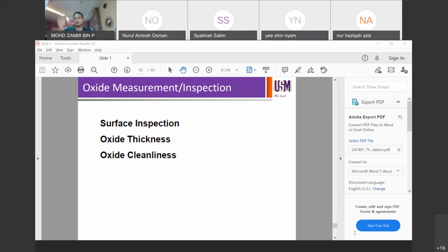So that particular lot is gonna be on hold due to the particle count failing the spec, right? Failing the process spec. So maksudnya selagi mana you tak troubleshoot the problem, whether it's due to the process or the recipe or the equipment or the gas or incoming problem, the wafers cannot proceed to the next processes. Okay, maksudnya duduklah kat situ sampai process engineers or equipment engineers come in and troubleshoot and find the root cause and solve the root cause and make sure that it doesn't happen again in the future.